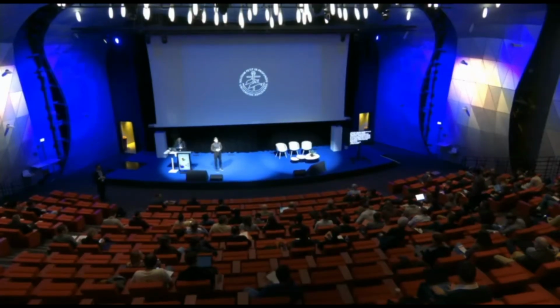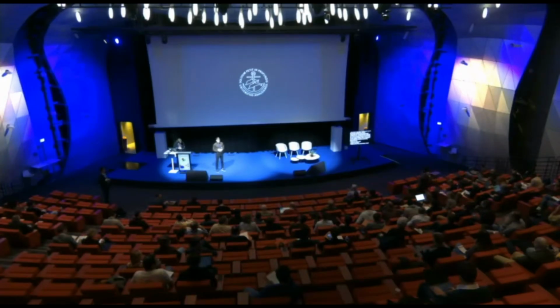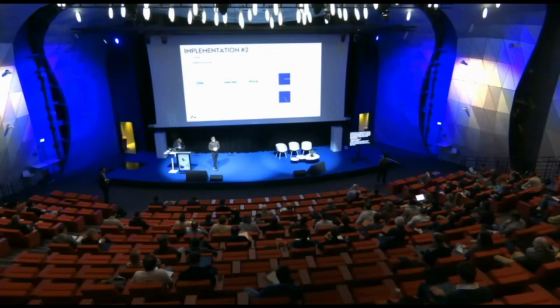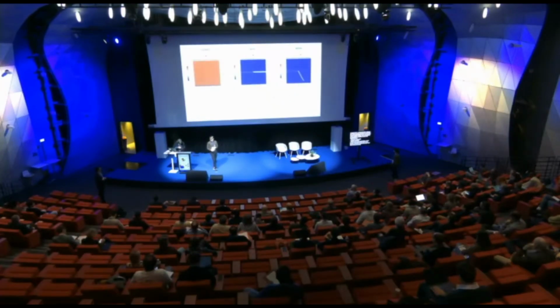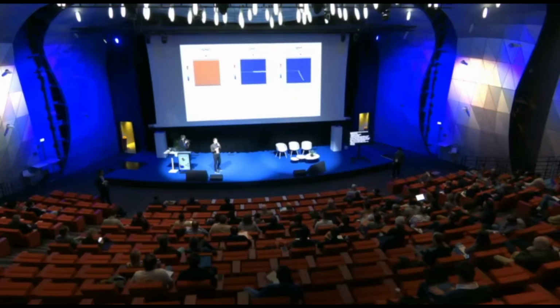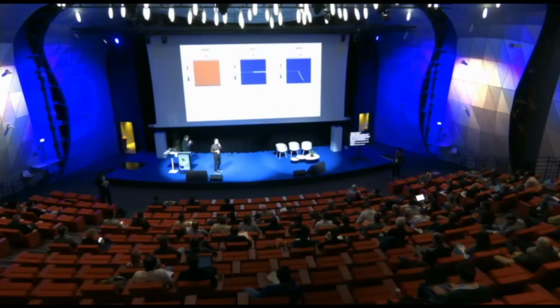I don't know if I missed a point, but I have a question about the result of the second trial. I saw a drop in the force displacement, a drawback. Can you just explain what it is? Which part are you talking about? The tensile, the middle one. Okay, so the drop in the force displacement is because that's where we have the crack evolving. But why do we have a drawback, not just a reduction in the force with a reduction in displacement at the same time? Did you force your convergence? So you're talking about the snapback?